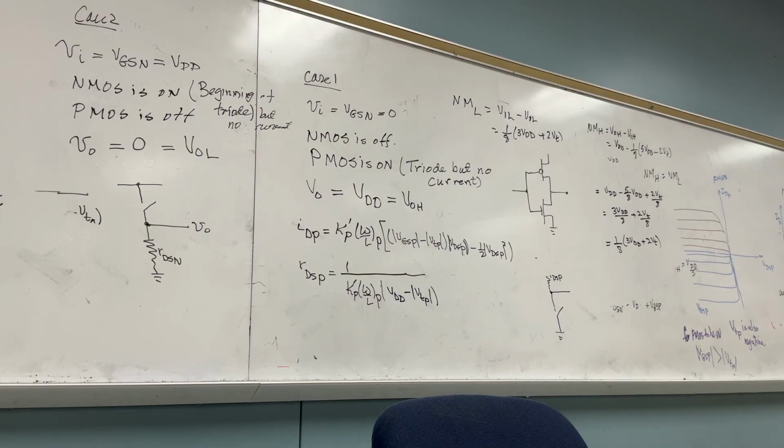Where do these capacitors come from? Inside the CMOS itself, inside the devices, there are parasitic capacitors. Do you understand what parasitic means? Remember those places where they create the enhanced channel and the gate, they create what is known as a capacitor when there is a depletion region between them.